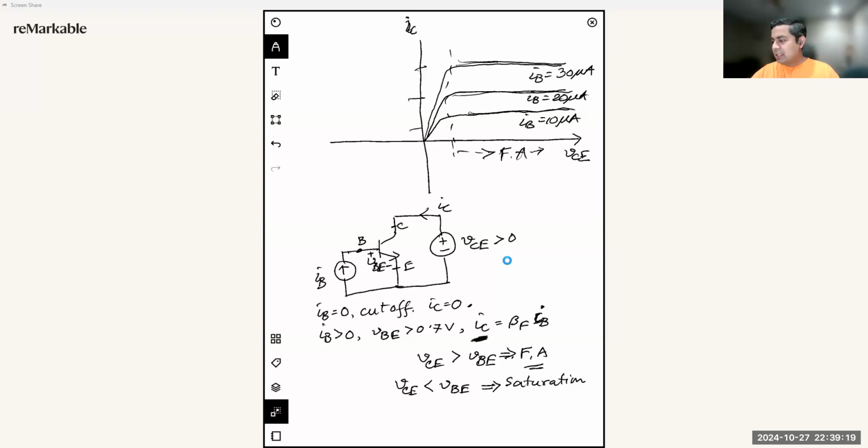Basically, as you can see, it has no effect on the collector emitter voltage. It's just going to be constant. And in the reverse active region, we are going to see similar behavior, like the current will start to increase in saturation. So this is our saturation region when both of the devices are forward biased. It's similar in the reverse direction also, but qualitatively the current magnitudes in the reverse active region will be much lower than the current magnitude in the forward active region.